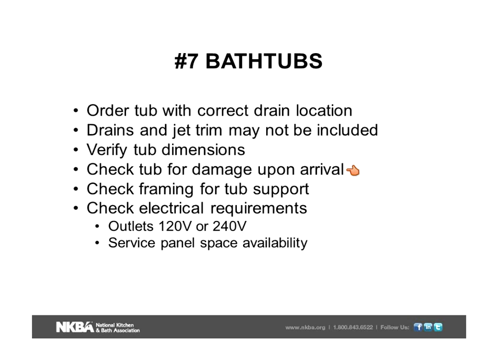A point here. When that bathtub arrives on the job site, and this is coming from a plumbing wholesaler, open it up and look for damage right then and there. If there's no damage, then make sure it's in a secure area where it can't be damaged. But once you open that box and there's damage there, and this is something that needs to be put in tomorrow, then it's too late to reorder. So check that damage. And again, that's not coming from a designer. That's coming from somebody that supplies a bathtub to you.